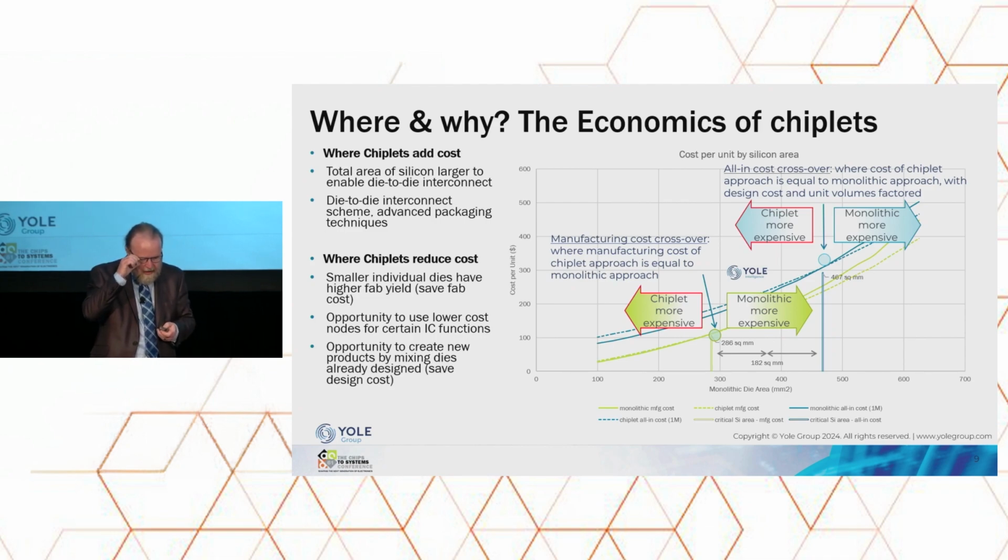And in terms of the die interconnect, there are some packaging costs surrounding a chiplet-based design versus a monolithic design. So there are costs involved. So it means that there is going to be a crossover point where those costs are less than the amount of money that you're losing based on yield, based on the tape outs, all of the other things associated with highly complex heterogeneous dies. And then on top of this, it's not just the manufacturing costs.